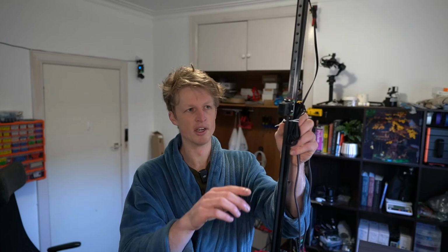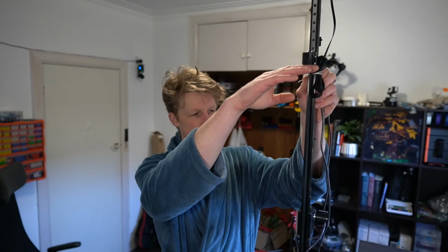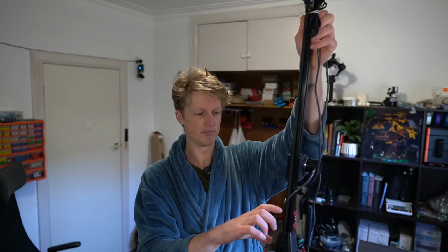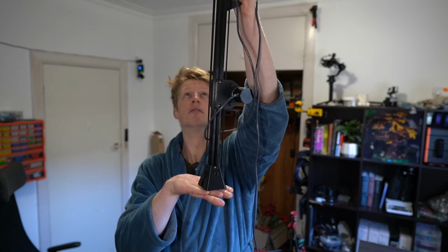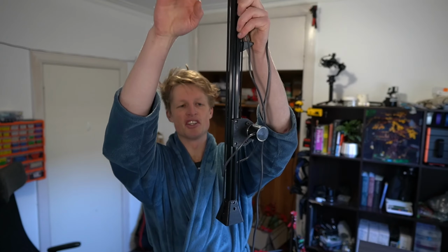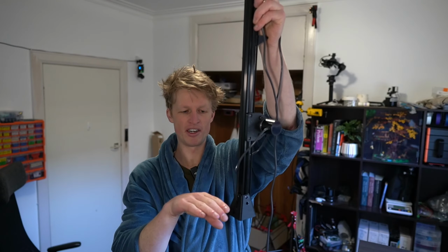The second step is to zero out this system. So I will bring this down to very, very low down the bottom, to some distance away that I know the length of. So I get a stick that I know the exact length of, put this on the ground, put the stick up, measure how tall that stick is and say, okay, this stick is 150 millimeters or whatever. That is equivalent to 5,000 ticks. So therefore, zero, the ground, absolutely flat, is however many, 5,000 ticks up.